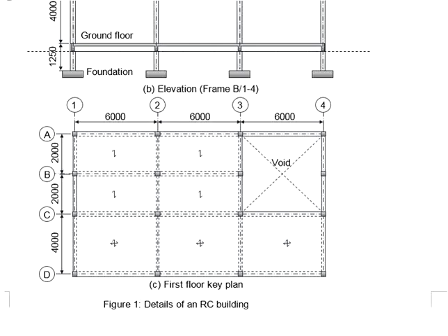To make it simple, you can imagine the distributions of the load onto the slab by drawing a 45-degree lines where they meet each other, and this will be the regions where the loads are distributed.